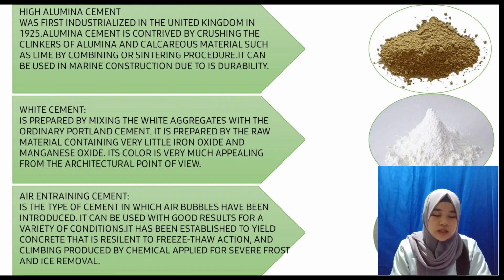infrastructure due to its early strength gaining property. It is also extensively used in making refractory concrete where it has to deal with high temperature. So this is the cement that can be used in high temperature places, those with high temperatures. It is widely used for the manufacturing of concrete and precast concrete beams.